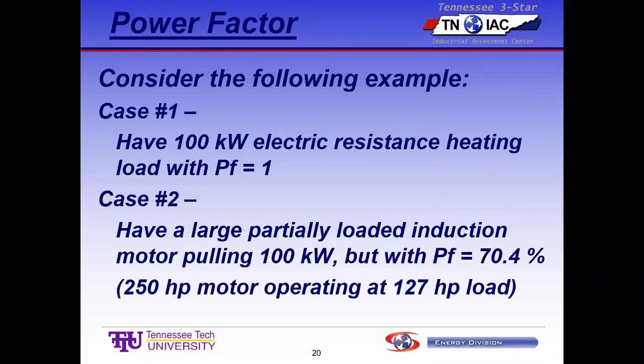It's going to pull 100 kW of power with a power factor of 1 because it's just a resistance load. Case two, which we'll compare that to, let's say we have a fairly large motor, say a 250 horsepower motor, but it's only partially loaded, to the point that it's pulling 100 kW of input power.